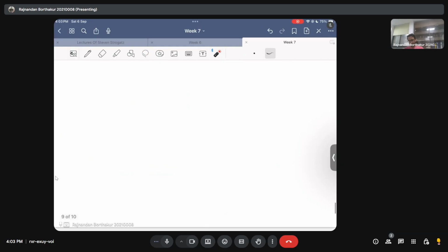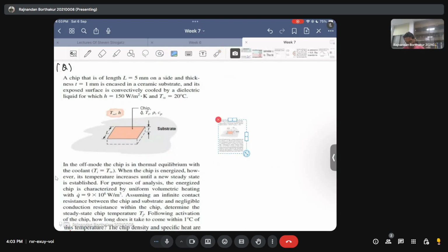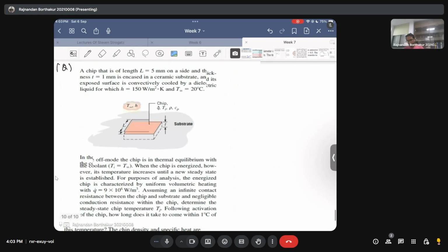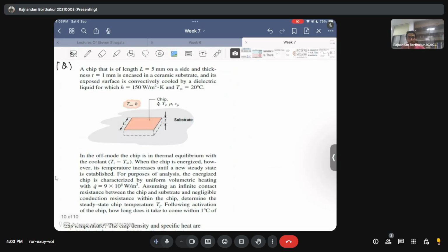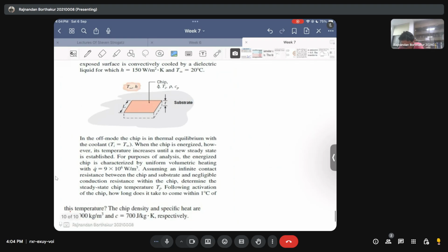And if this is clear, we will now solve an important problem associated with this lumped body. What I was trying to say is that in this problem, you can understand the effect of heat generation in a lumped body, and you figure out that we cannot directly apply the form of theta by theta i equal to exponent of minus Biot times the Fourier number, because there is heat generation taking place, and we need to start from first principles. Okay, but before this, I would like you to actually go through this problem once.